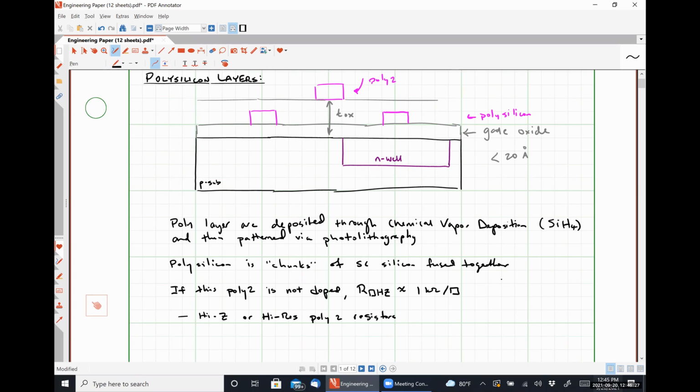So the space charge layer at the low potential side, or no potential difference side, so the 0 volt side, is going to be at an unbiased capacitance width. And on the biased side, the space charge layer is going to be a lot larger, right? Which means the capacitance over the length of the resistor changes. And the resistance over the length of the resistor also changes because the thickness is no longer uniform, right?